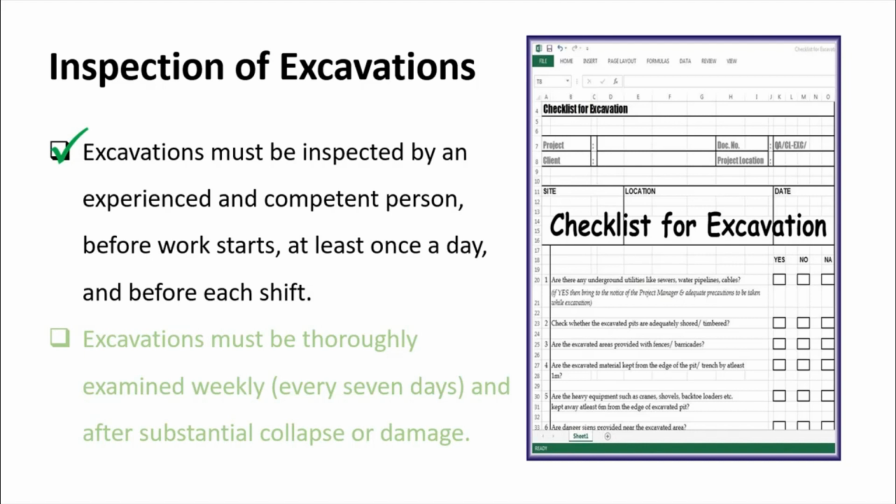That means the people doing the inspection have the experience and know the hazards of excavations. They should use the checklist for the excavation so that they will not miss anything. If they have the checklist, they can check everything on the list before work starts, at least once a day, and before each shift. If they find something wrong on the excavation, they should report it to the next shift so that they can immediately take action.